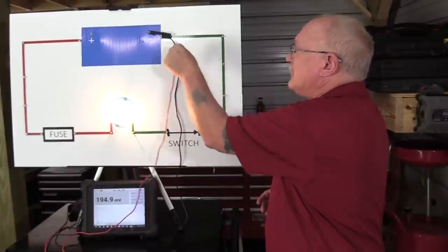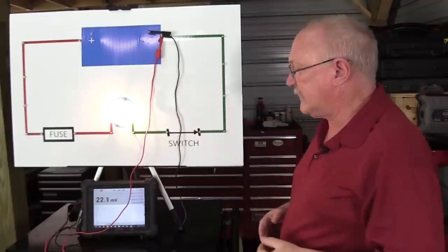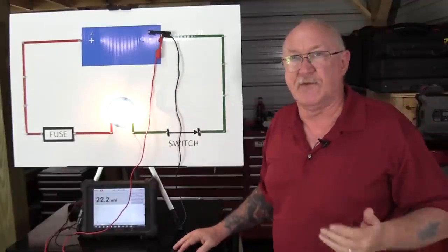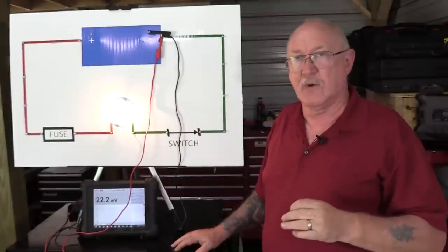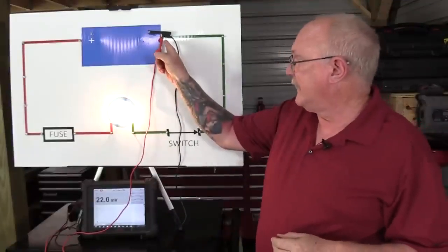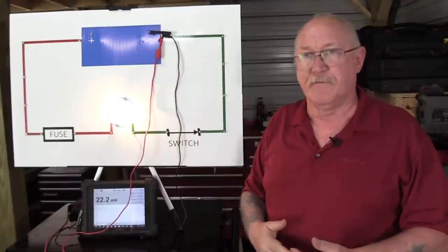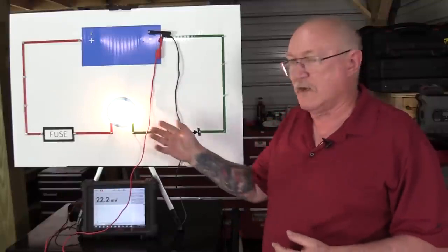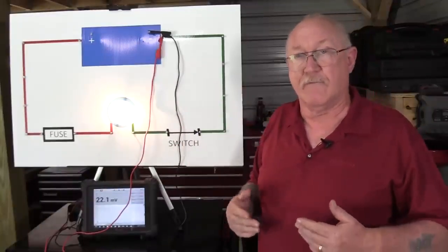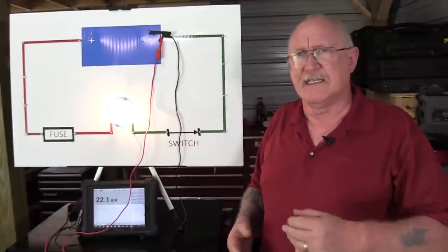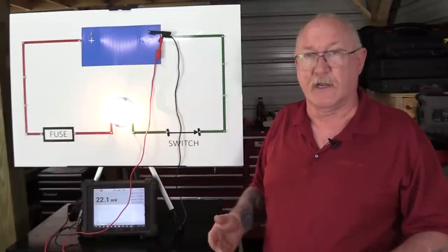And now we're going to come right where we started before, that simulation between the battery cable connection and the battery post itself. And look at that, we're down to about 20 millivolts, almost nothing. Where would that other 20 millivolts go? That little tiny source of resistance between my two meter leads, that's where that's being used. Now, as I said before, what we saw across the load, across all of the sections here for that matter, is called voltage drop. And that's a testing method that we can use to help us find the source of unwanted resistance in the circuit.